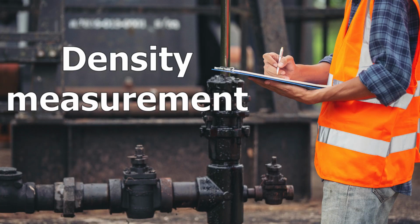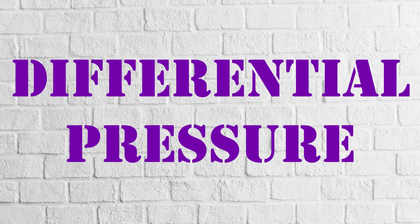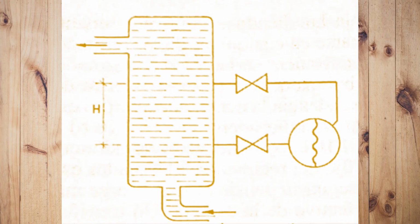Welcome to my channel. Today I'm gonna talk about density measurement by differential pressure. In this method, 2 points are fixed in the tank or in a vertical pipe of the process, and a differential pressure instrument is connected to them directly or through a measurement chamber. As the difference in height in the liquid is fixed, the only variable that alters the differential pressure is the density, as long as the temperature does not vary.